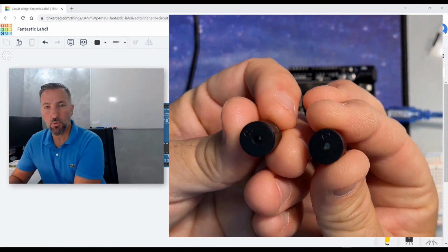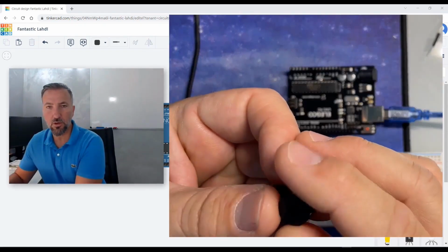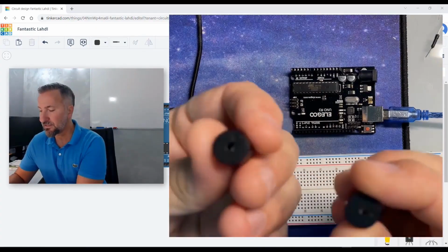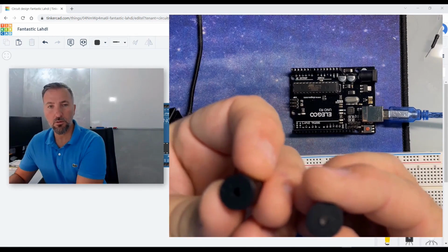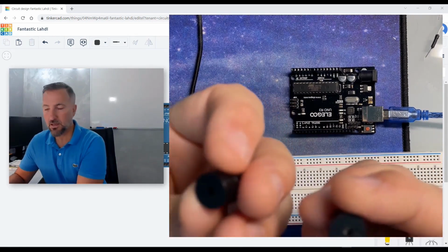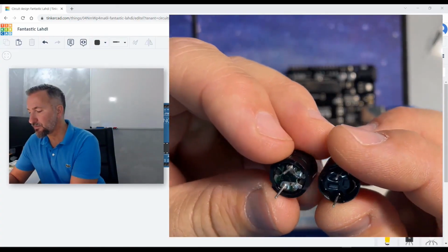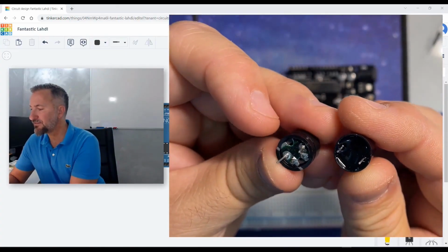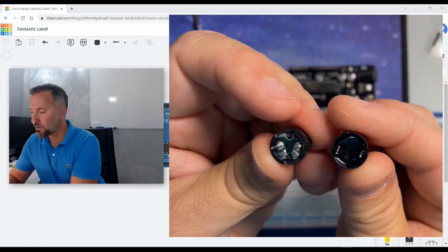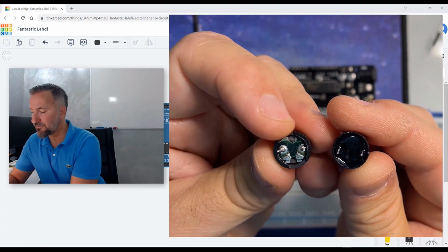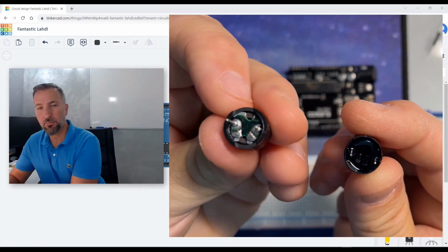From the top view, the active and passive buzzers are practically identical. Both, when powered on the positive pole with a positive voltage, for example with the digital output of one of the Arduino pins, such as 5V, and with the negative to ground, will obviously emit a fixed sound with a fixed frequency. But only the passive one allows us to change the frequency. You can see it on the left one: it is open, not sealed, with the PCB visible, and thus the green edge with the soldering here. This is the passive one.